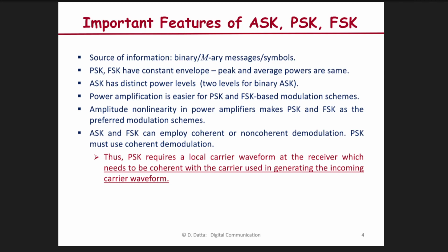I will show you how M-ary is used, when M-ary is used, what is the purpose of that, what are the challenges, and so on and so forth. We'll discuss that. Another thing which I discussed yesterday, I repeat: PSK and FSK have a constant envelope.